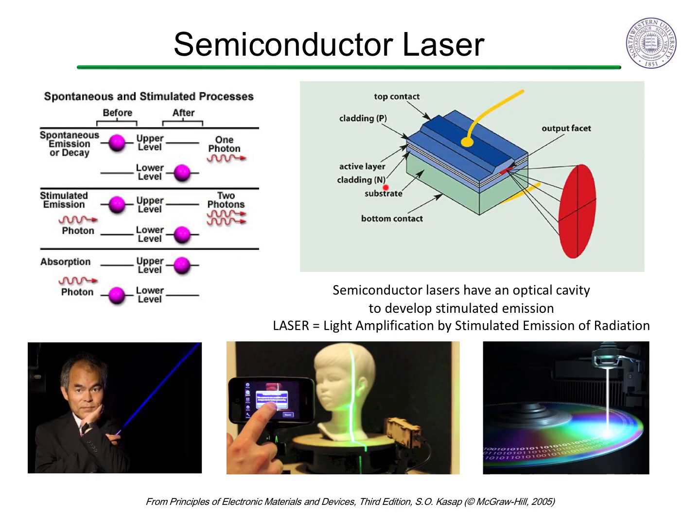By engineering an optical cavity around the active layer, the light emission can stimulate further electron-hole recombination, which is the basis of a laser. Whereas spontaneous electron-hole recombination leads to light with random direction and phase, stimulated photoemission produces light with the same phase and direction as the stimulated light. The resultant light has superior coherency, which enables the beam to remain narrow over large distances and allows extremely short pulses for use in optical scanners, memory, and communications.